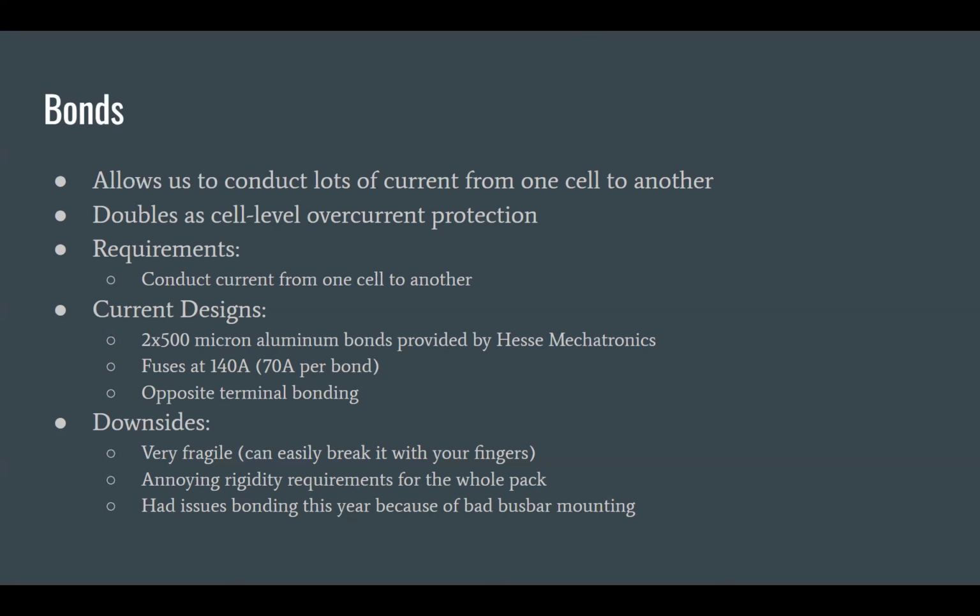Okay. My explanation was going to be that the BMS in the segment actually doesn't have the power of the pack going through it. This is just the monitoring board. It can't disconnect things. The main board can disconnect the entire pack, but not a single cell. And then you can talk about rules. All right, let's talk about rules.